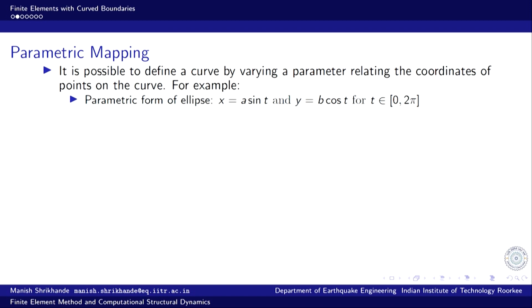But an important point to note here is, although there are two coordinates, knowing the semi major and semi minor axes, I just need to vary one parameter t and the entire ellipse can be traced out. And this actually forms the basis of the actual construction of an ellipse on the ground or on a field. So, how to draw an elliptical figure, this is one of the ways in which we can actually trace out an ellipse on a field.